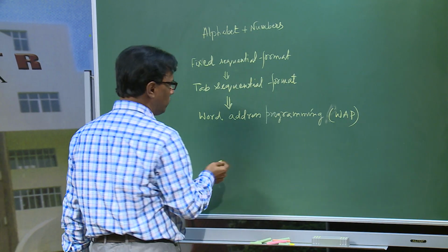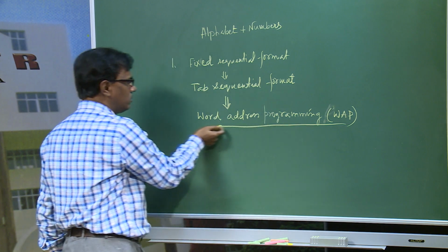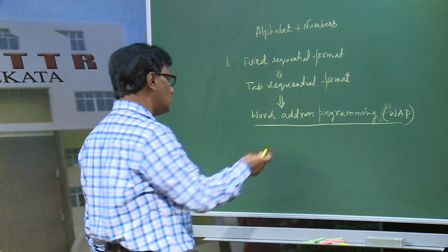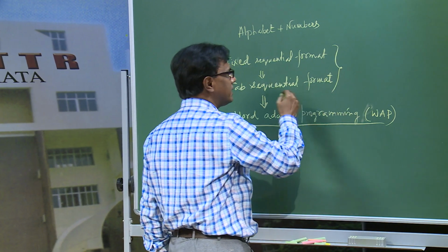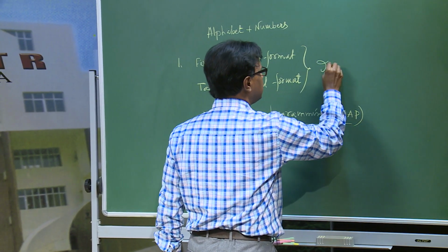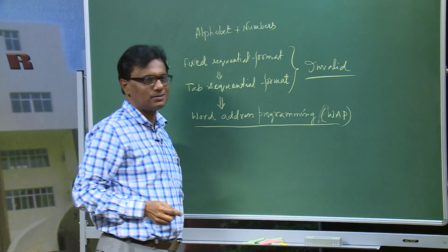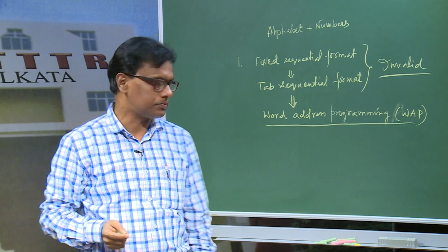In fact, in almost all CNC machines now, word address programming is used. The other two types of programming techniques have become invalid nowadays. Nobody uses these. No manufacturer is following these programming techniques.